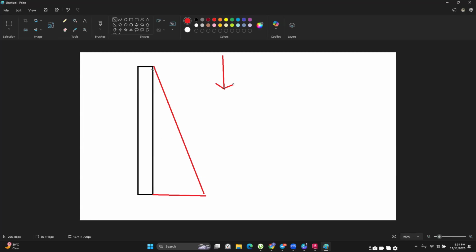So we want to ensure that whatever we model actually makes sense. We do not want to be in a position where the soil distribution looks like this, number one. So let me do something here. Okay, so this is the ideal situation where this is the inside part of the wall, and this is the outside of the wall. So the soil is here. We want to ensure that our pressure is pushing the wall inside. There are things that I want us to avoid.